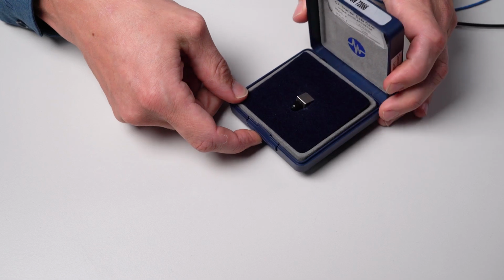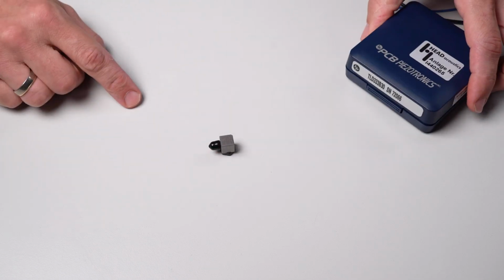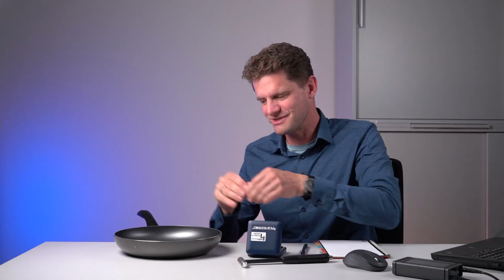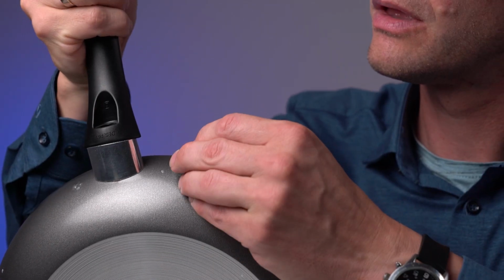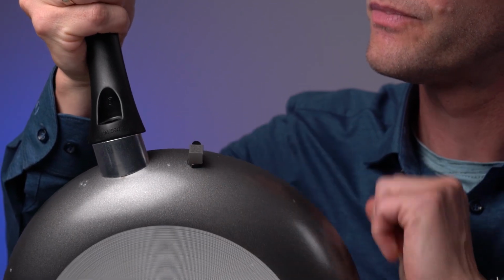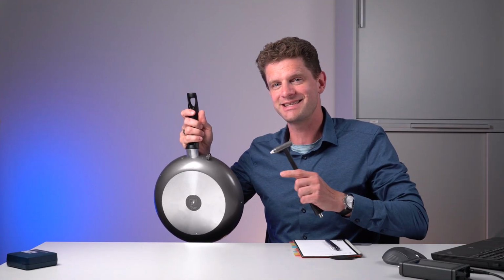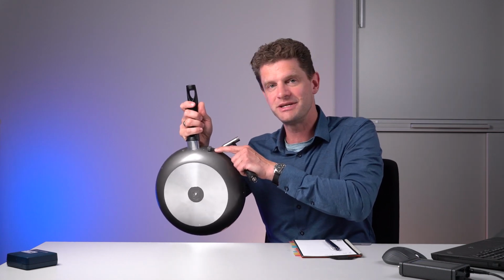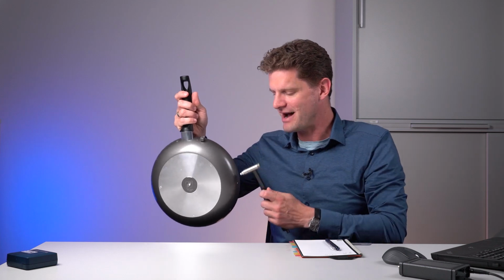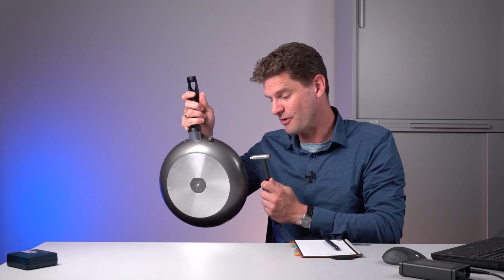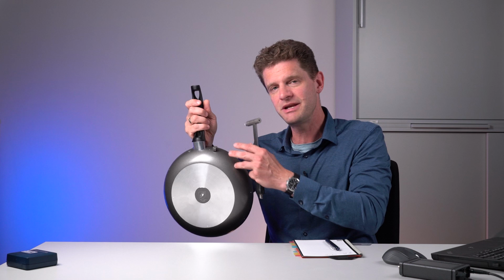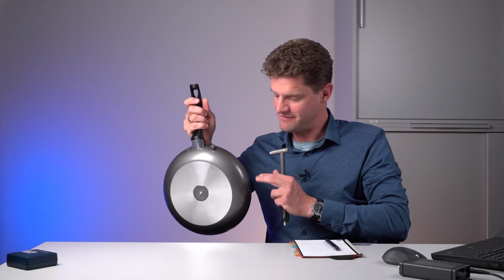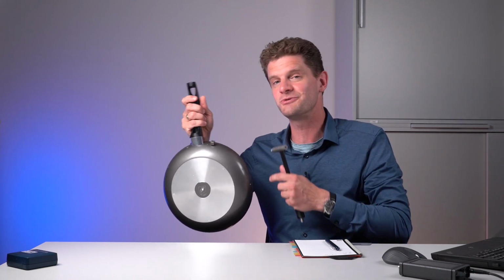We use an accelerometer, really small, tiny symbol, doesn't have a lot of mass, so there's no change on the object, and we can glue it on our test object. So our FRF is now the relation between the output, as we learned before, now in meter per second squared, divided by the input. Now this is force. And this relation between amplitude and phase will be the FRF from this point to this point through the pan.